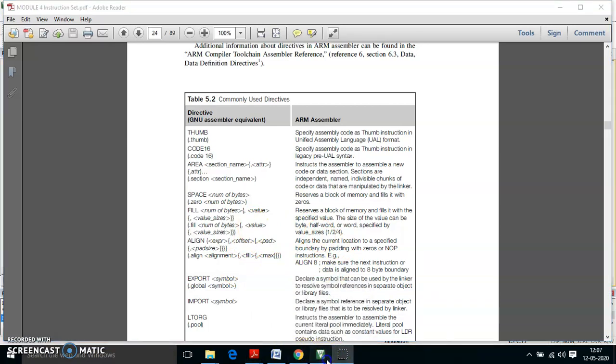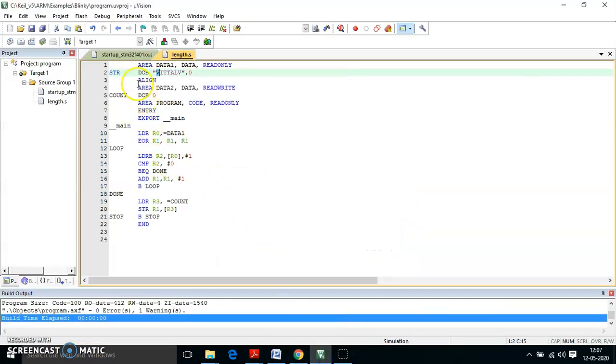Now let us go to the program. We have opened another area which is also connected to the data memory, saying that we are going to read and write. We have already fetched the data, but after the characters in the string have been counted, the result has to be written in some other place. So we have opened a label called COUNT with DCB. Again it's going to be a byte value, and it keeps incrementing based on the number of characters we have loaded. For example, if we have loaded 7 characters in the string, it has to be 7.